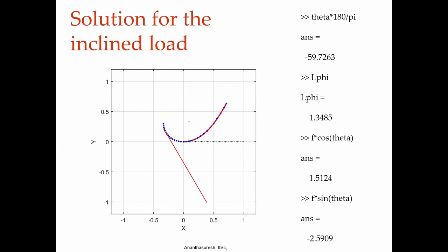Once we get that phi, L phi can be obtained by integrating from 0 to that phi, the elliptic integral of the first kind, where the square root is there. Then I get this L phi, that is the arc length all the way, the whole length or length of the original beam. Now, if there is a force P here, then we need to resolve a component along this and perpendicular, those are these. If I apply these forces, it will deform to this shape, the same thing that this beam which is fixed here would do, that is elastic similarity.